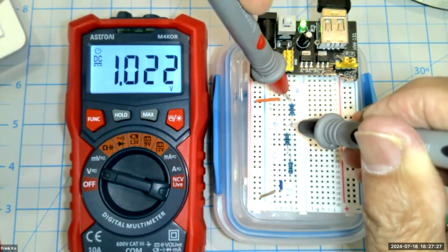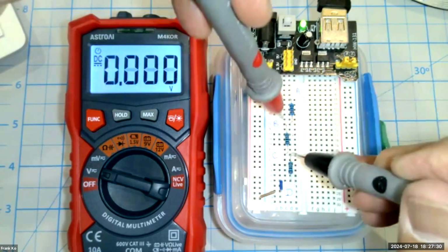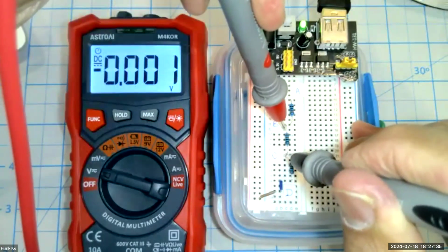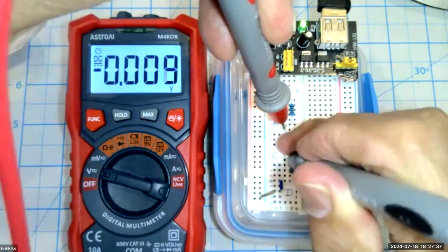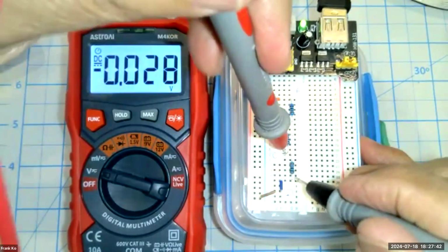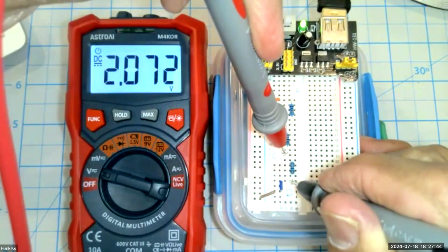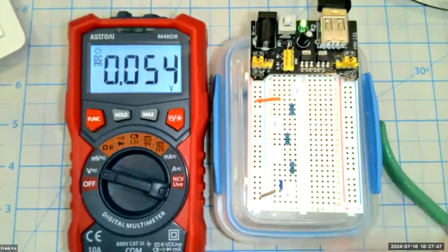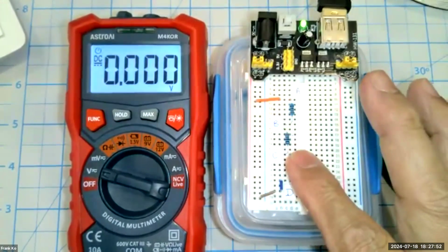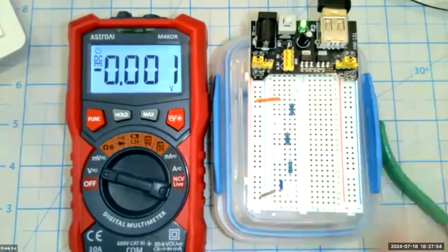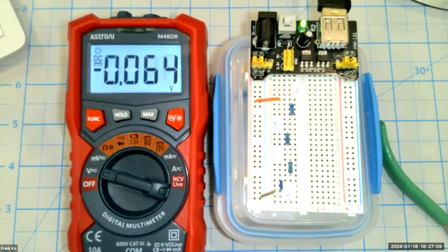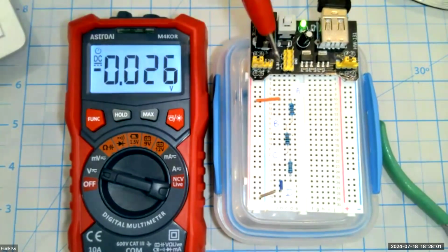So we have basically 1 volt across R1 and basically 2 volts. Well, just keep squishing these wires. Okay, 2 volts across R2, and basically we should have about 2 volts across R3. So our voltage divider is built properly for the ohms being in the right places, and the voltages across the resistors being correct. Now we're going to make the measurements of our technician point voltages with respect to ground.